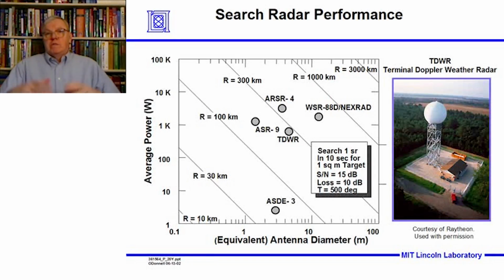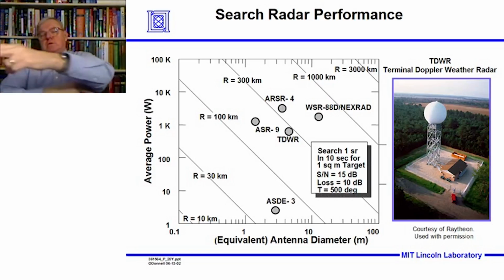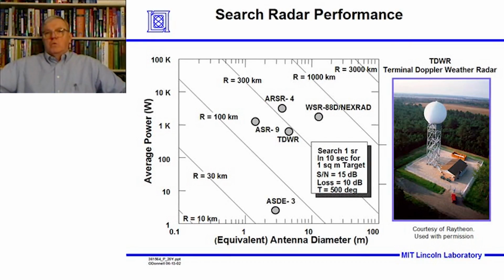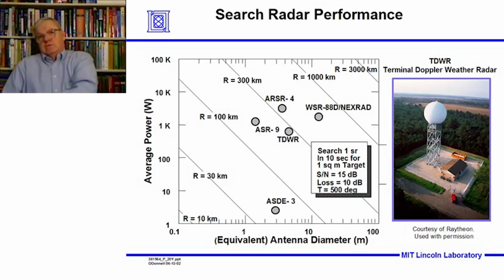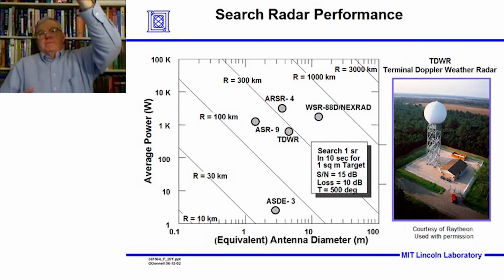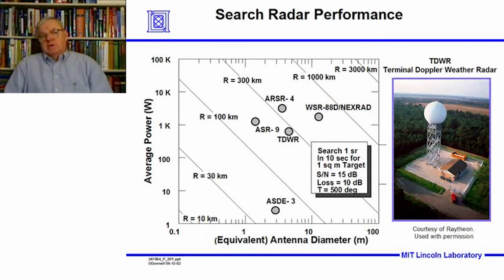The characteristic when there is a wind shear in the area is, think of a circular area where the wind is coming up and then going down. On one side, as you're coming in, it's going up, and on the other, the wind has a downward velocity. When pilots are coming in for a landing, they sense this weather pushing the aircraft up, and they want to stay on the appropriate glide slope. So they push the aircraft to compensate, with the elevation equipment on the wings, so that the aircraft will go down faster.